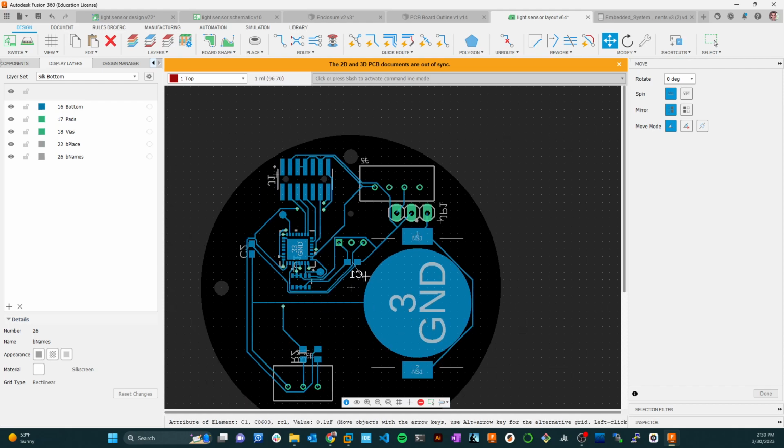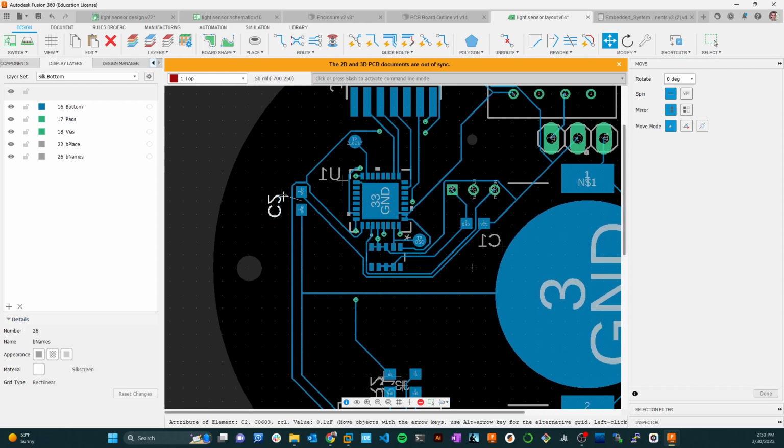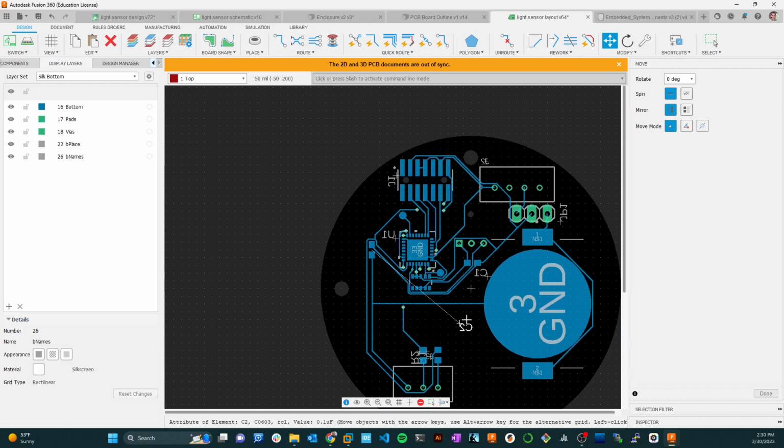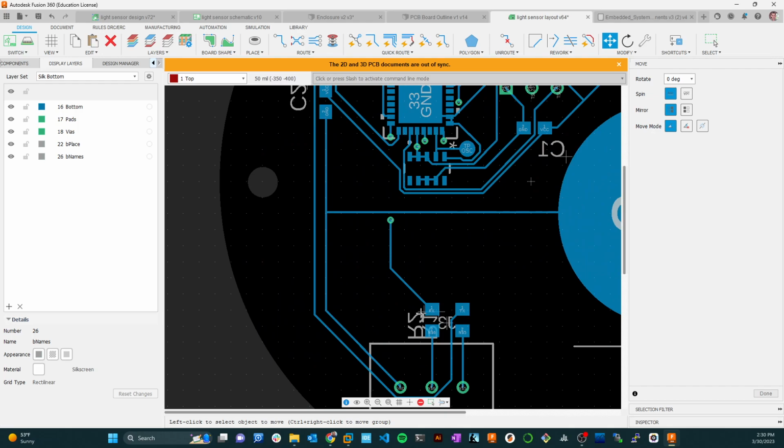I think what you really want to do is, to the extent possible, avoid this hitting copper. So we'll put it over here, something like that. If we can get this off of any copper at all, it'll be the best looking sort of job if you can just keep it clear of copper. Certainly vias, holes or vias where the paint will just get sucked down in the hole. Something like that.